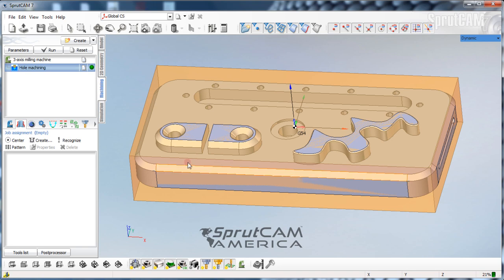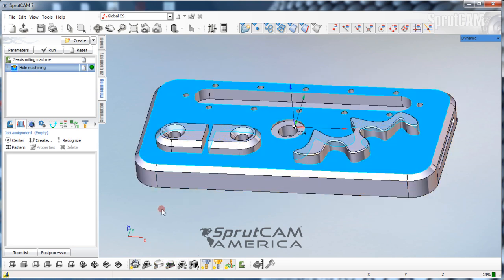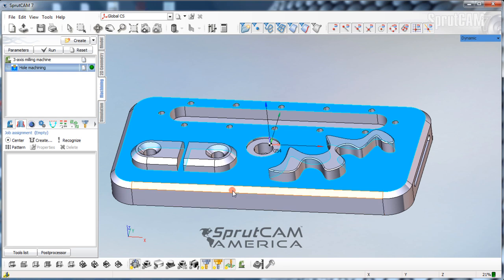So now that I've selected that button, you will see that I can highlight faces or anything else. Now, if for some reason these other buttons are all turned off and you have Geometry Model Visibility turned off, you won't see anything. So that's kind of a baseline to put yourself at: click off everything. Then if you just click Geometry Model Visibility, you will see the model and be able to pick things.